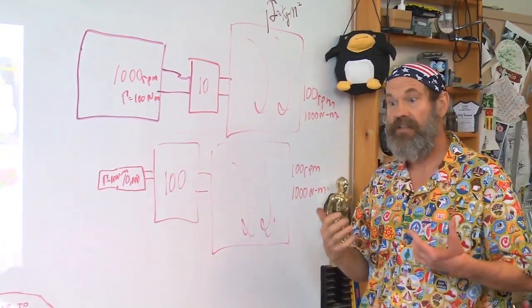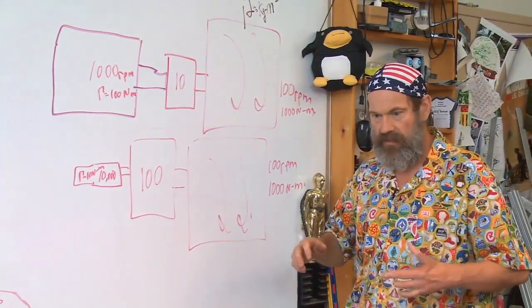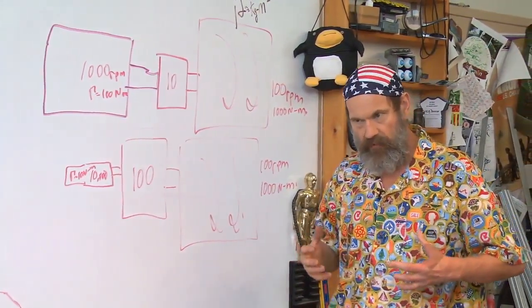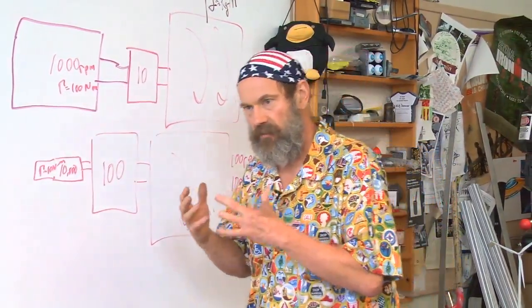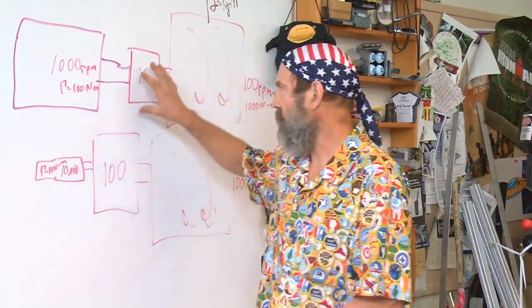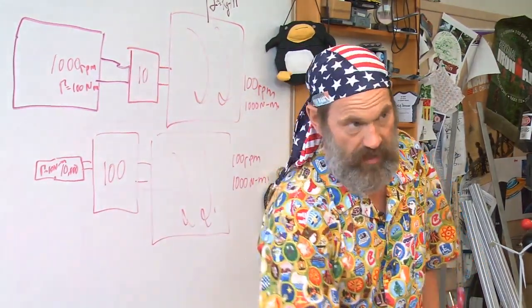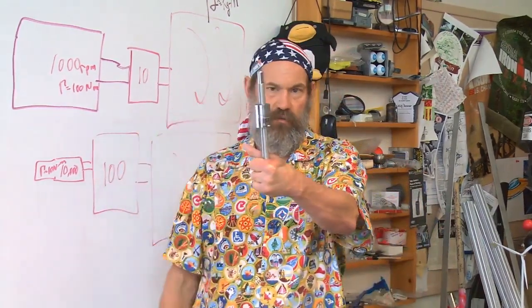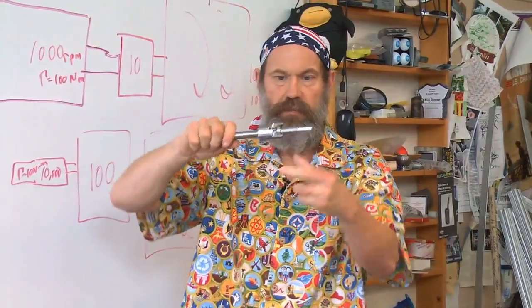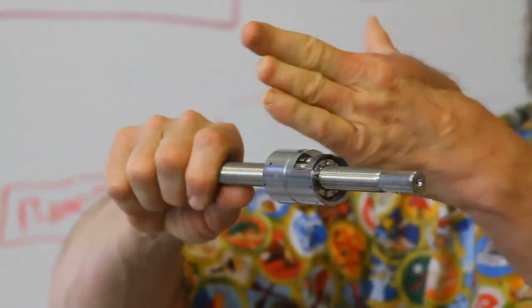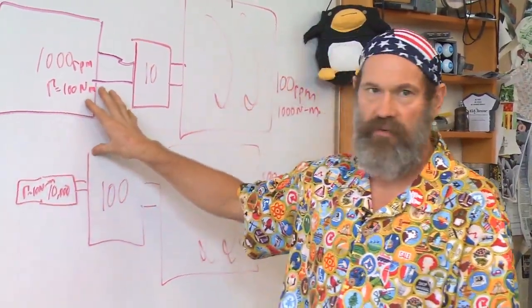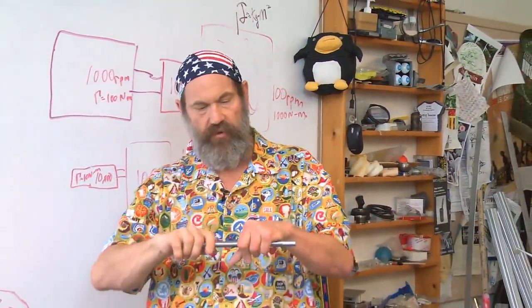So that's the logic and the rationale behind how we're going to take from the power source an appropriate transmission and get to the output load. It can be a rotary motion gearbox. The same type of analysis works for a screw, which is a transmission. Remember, for a screw, there is a transmission ratio of one rotation equals one lead's worth of motion in translation. So everything we talk about for rotary motion, there's an analogy for rotary to linear motion.